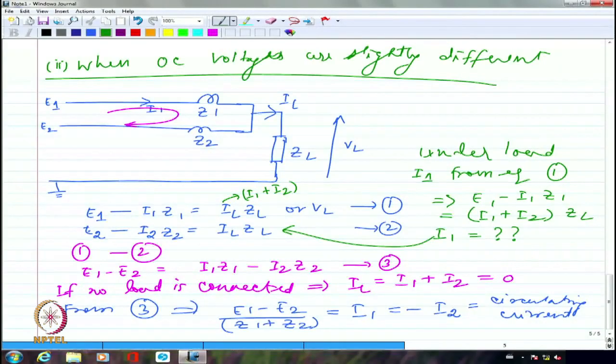That's about it. Whenever you have unequal voltage ratios, still you will be able to get how the loads can be shared by using the expressions that you guys will complete, that derivation, right? So, parallel operation of transformers is possible whenever the voltage ratios are equal. But even if they are of different capacity, I can definitely operate a 100 kVA transformer in parallel with a 50 kVA transformer. No problem.